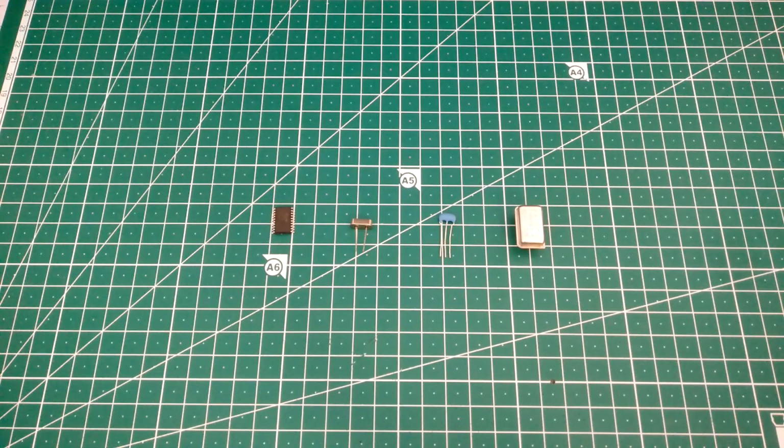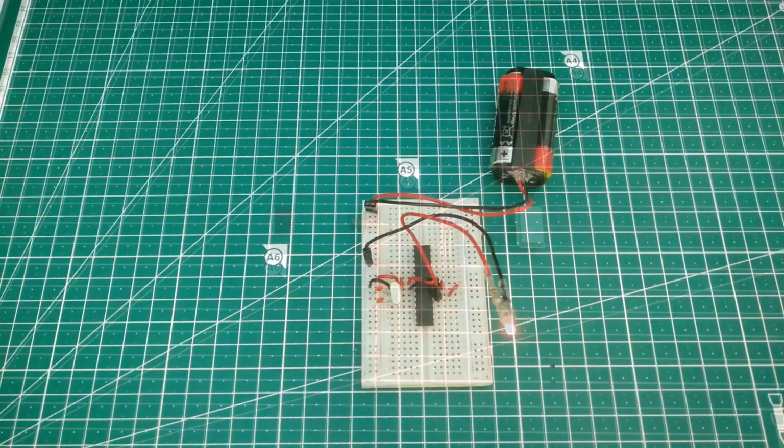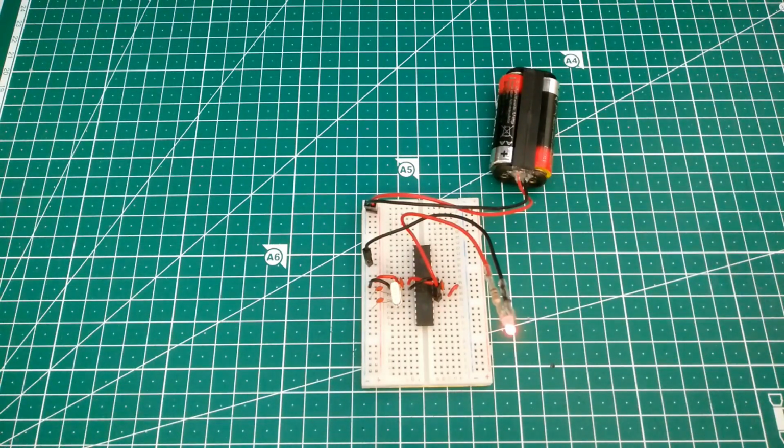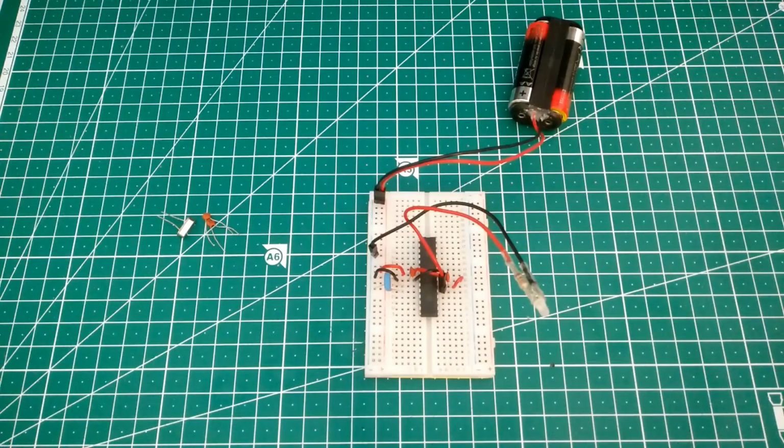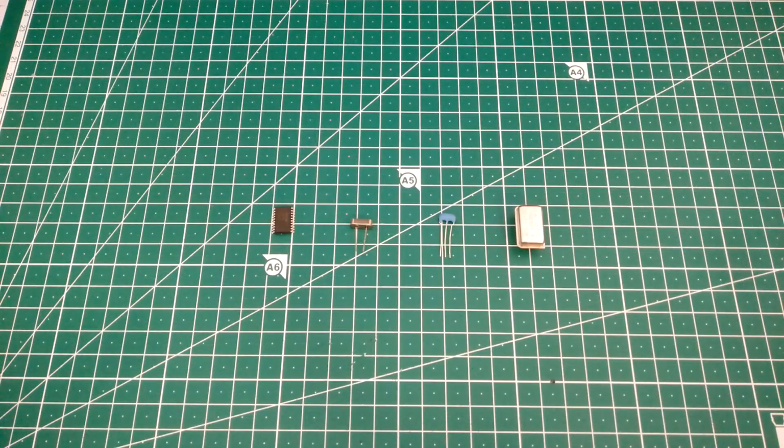Whilst the ceramic resonator is useful because it is actually a direct replacement to a crystal and its load capacitors, so you can just plug it in the place of a crystal, and the extra leg that it has is the leg that the load capacitors would have wired to ground. That's the extra leg in there. It doesn't need load capacitors. So whilst it is a direct replacement, it's not usually worth it because it's not really that much cheaper.